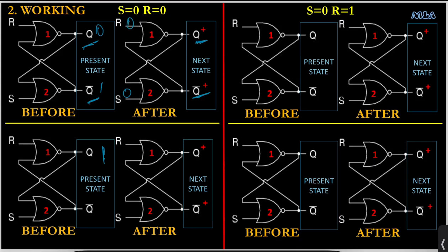Fine. So as we discussed earlier about the working of a NOR gate, if any one of the inputs is 0, we will not be able to say anything about the output until and unless we have information about the other input. Now here the other inputs are the feedback inputs, right? And the feedback inputs we have defined Q as 0 and Q bar as 1. Q is driving gate number 2.